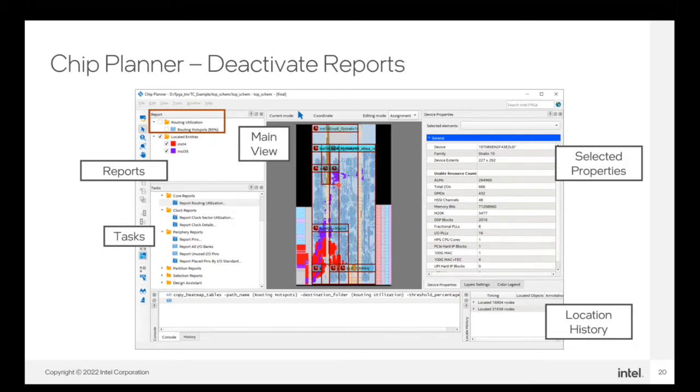With Instance 35, I can see that Instance 35 is kind of spread out all over the chip. It's nice to see cross-probing your modules into Chip Planner this way, to see if communication for particular modules is happening the way you expect. Now, in my opinion, the tools do a very good job at placing and routing your design.